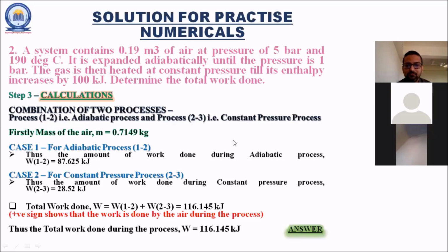Okay, roll number 54, can you explain the second process again? Okay, so the second process, that is the constant pressure process, is the process going from 2 to 3. Initial is 0.2 and final is 0.3. Firstly, using the adiabatic process, I have calculated the final temperature, that is T2.